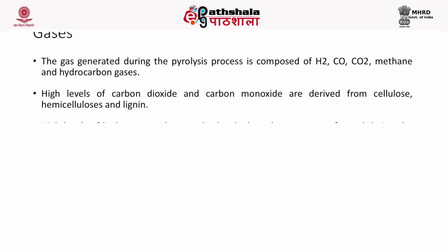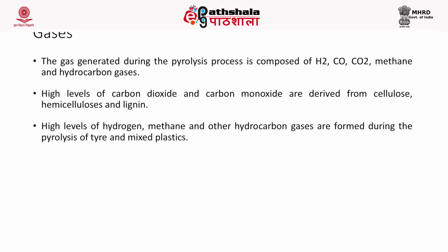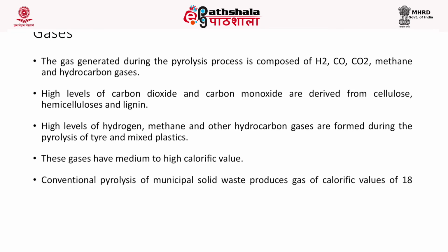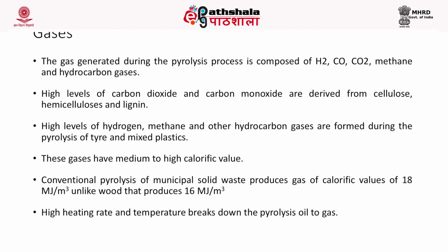Now the gases generated during the pyrolysis process consist of hydrogen, carbon monoxide, carbon dioxide, methane and other hydrocarbons. High levels of carbon dioxide and carbon monoxide are derived when the waste material contains cellulose, hemicellulose and lignin, that is your biodegradable material. High levels of hydrogen and methane and other hydrocarbons are formed during the pyrolysis of tyre and mixed plastics. The gases that are produced at the end of pyrolysis have medium to high calorific value.